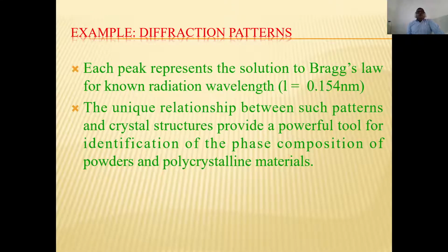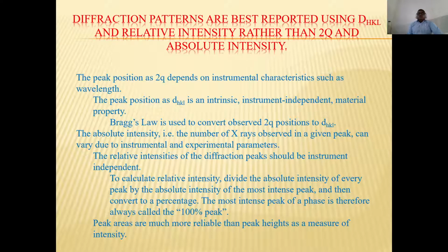Now, example diffraction pattern. Each peak represents the solution of Bragg's law for a known radiation wavelength, that is lambda is equal to 0.154 nanometer. The unique relationship between such a pattern and crystal structure provides a powerful tool for the identification of the phase compositions of powder and polycrystalline materials.